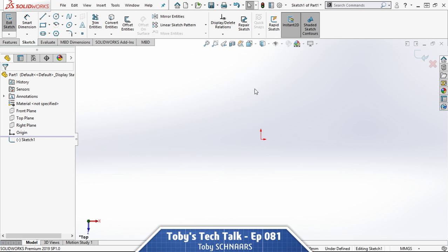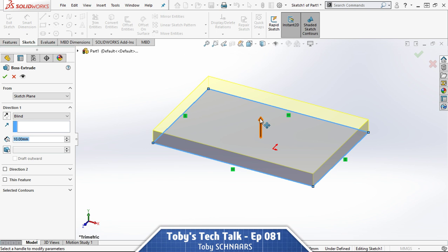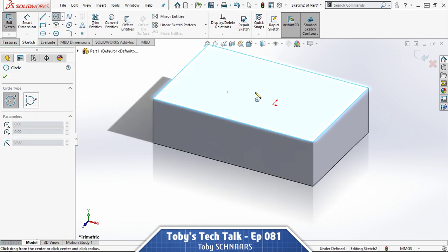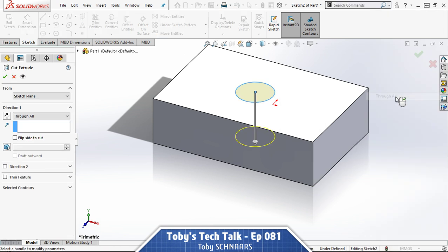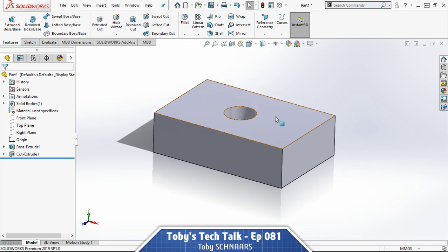So now whenever I'm working in sketch mode, I can sketch a rectangle, hit the S key, jump right into the extrude command, create an extrusion here, go back to sketch mode, begin a sketch, S key, circle, begin a circle there, go into my cut extrude command, right mouse button through all, and finish that cut extrude. So things are already starting to cruise along here.